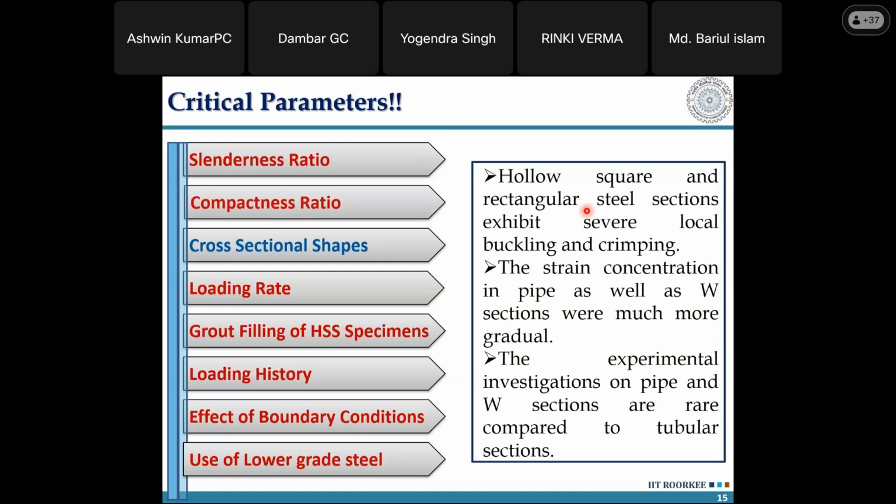Now, why people go for it is because there is a fixed dimension, the width and the depth. Along the width and the depth, you can easily locate the center of that particular side, cut a slit inside it, and then insert the gusset plate into that slit. That is how the connection is generally made. We have diagrams coming up where you'll understand what I'm saying. But in that particular case, box sections are much more convenient in terms of connections.